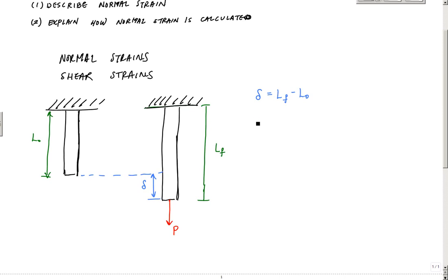So here, this normal strain, for which we use the symbol epsilon, this is the way I write Greek epsilon right here, is the change in length divided by the original length right here. And this is my normal strain. And the way I've done this for an axially loaded bar, this gives us a really good feel for the average strain across this element.